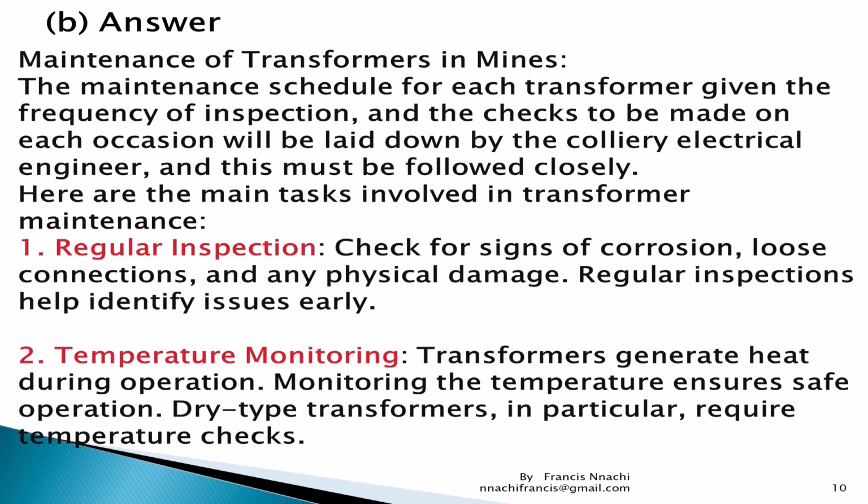Okay, number one, there should be a regular inspection. You need to check for signs of corrosion, loose connections, because if there's any loose connection, remember the area is explosive, so we don't want loose connection. We must check any physical damage.